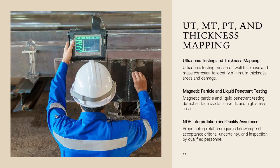Magnetic particle testing and liquid penetrant testing are surface examination methods used to detect cracks, particularly in welds, nozzle connections, and areas of high stress. Selection of the appropriate method depends on material type, accessibility, and the nature of suspected damage.